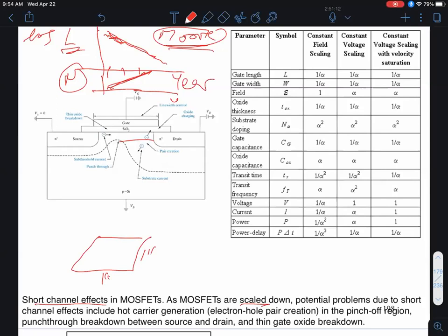But it also turns out that if you make the transistors smaller in size, the performance of the transistor also improves. For instance, Branch brought up this business of high frequency performance, right? Now let's see physically, what would you expect would happen to the high frequency behavior? Well, the carriers have to travel from the source to the drain, right?